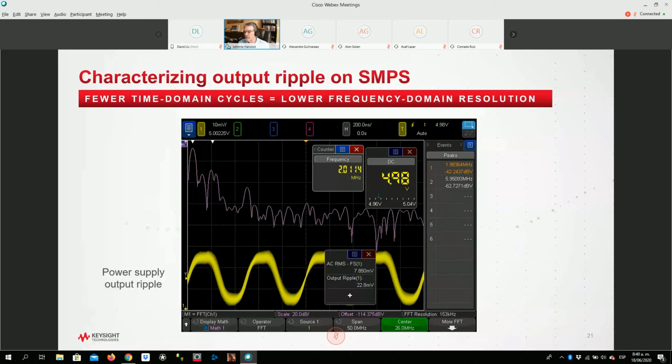There is about 20 millivolts peak to peak output ripple. As you can see, I've got my voltmeter turned on up here, my DVM. You can see it's measuring 4.98 volts. This is a 5-volt power supply. But you can see this ripple that's happening at 2 megahertz. That's the switching rate of the power supply.